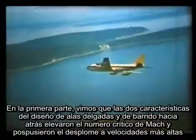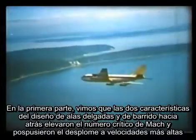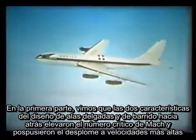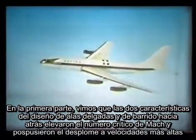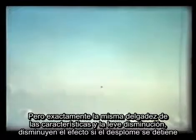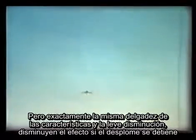How can these troubles be met? In part one, we saw that two design features, thin wings and sweepback, raise the critical Mach number and postpone the shock stall to higher speeds. But exactly the same features, thinness and sweepback, lessen the effect of the shock stall itself.